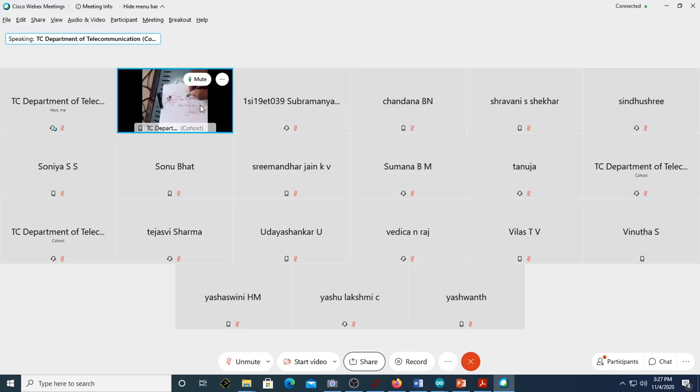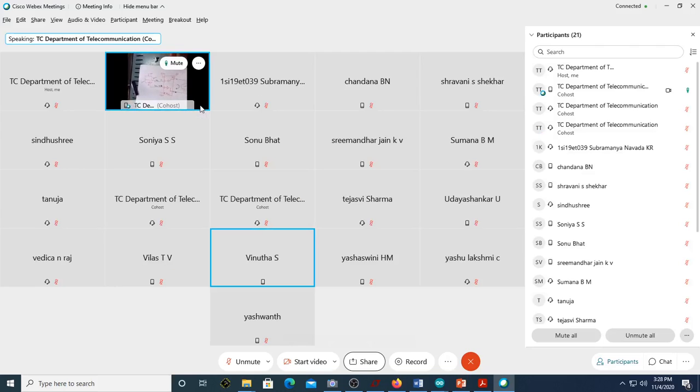Now, when this is high and this is low, that is when I make this low and this high. If I make both of them high, what will happen? Both of them are trying to source. The motor will not run because here also it is 12 volt, here also it is 12 volt. There is no potential difference across the two ends of the motor. It will not run because current is not flowing.